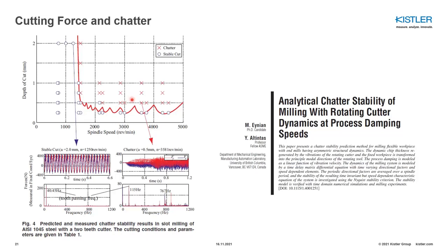you have unstable. So if you look at this part here, the force measurement, when you are measuring forces while making the machining operation at a certain cutting condition, you will have stable conditions. So you will have a typical noise level or dynamic, so to say, in milling. But if you are in the unstable regions, then you will see the chatter.